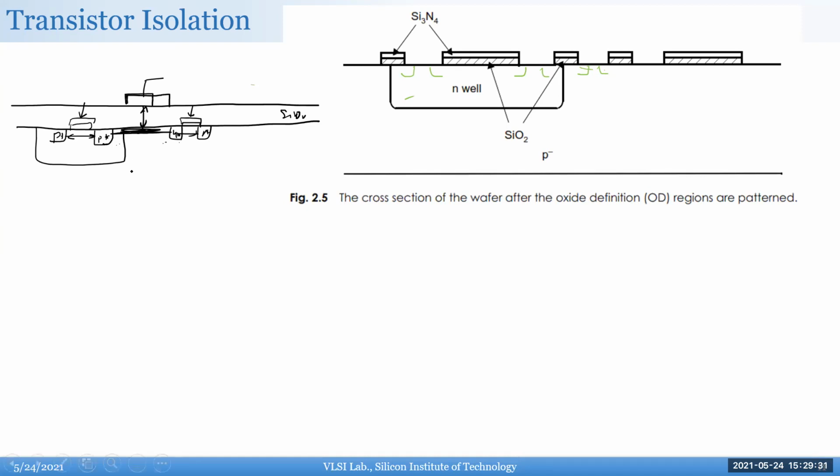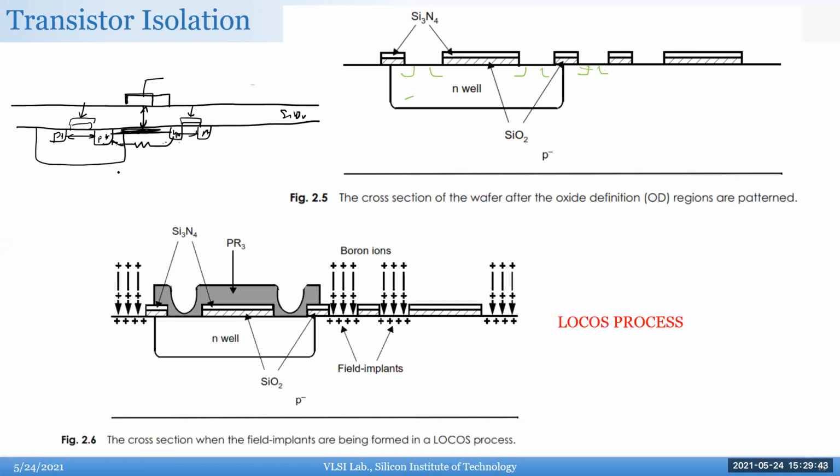Plus, you don't want to start cross-talking because of the substrate itself, because this substrate just looks like a resistor which is connected from here to here as well. So the way it is isolated in LOCOS processes, and this will be more clear tomorrow when we start talking about calculating the VT, the threshold voltage for MOS devices, you just kind of take it for granted here.